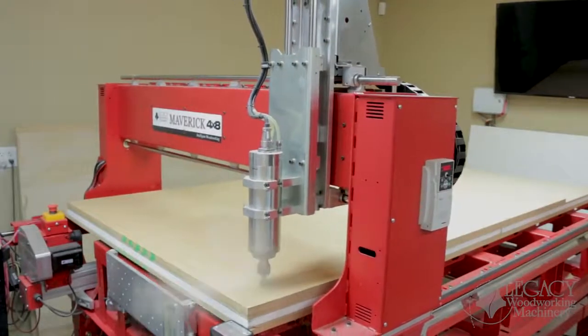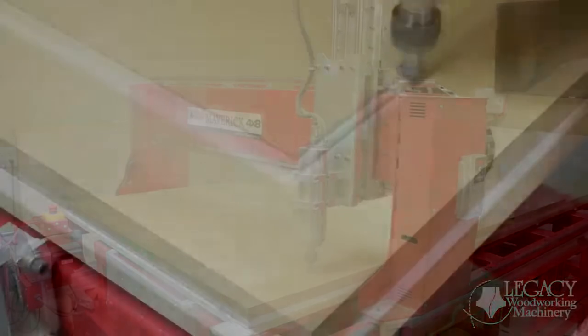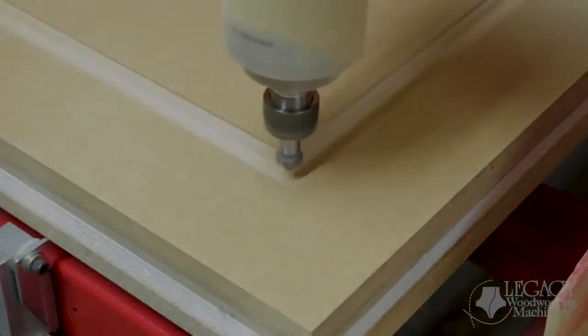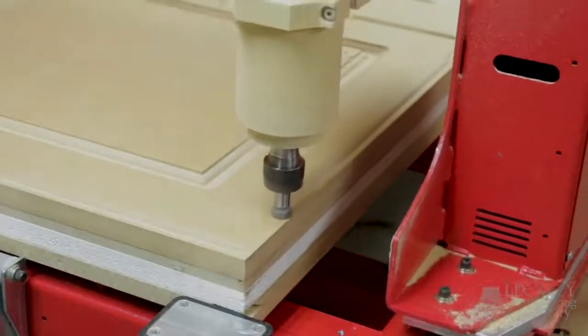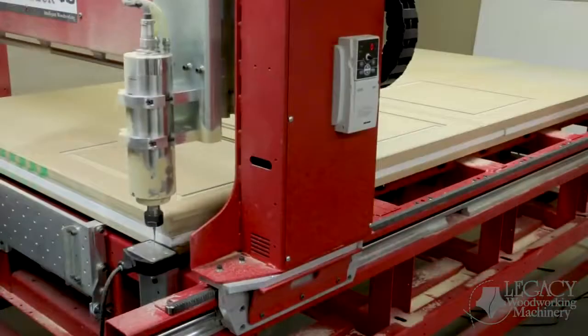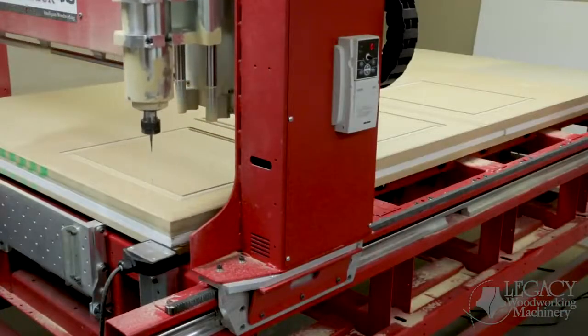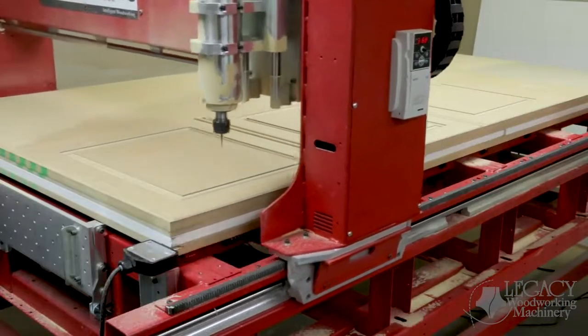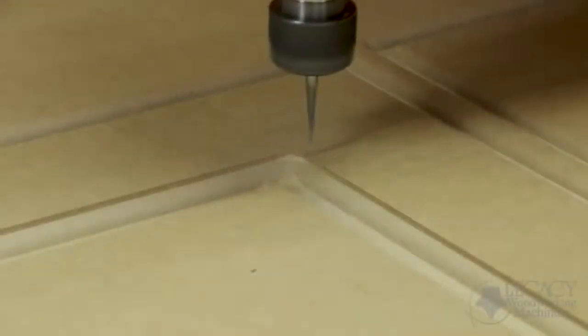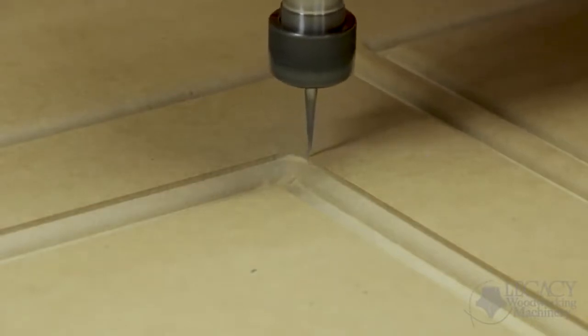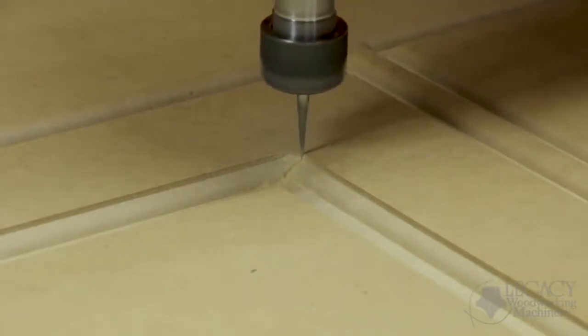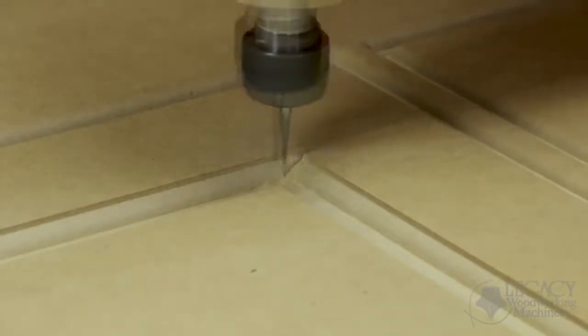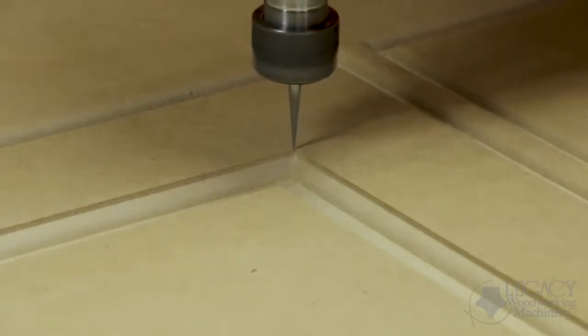The first cutter is our plunge flat roundover cutter with a 1/4 inch radius. This performs the inner and outer radius cuts of the door panels. The second tool is a tapered ball nose end mill with a 32nd inch ball nose. This cleans up the corners where the radius was left behind and shows that there are times when you can combine router bit profiles and raster carving to give you the best of both worlds.